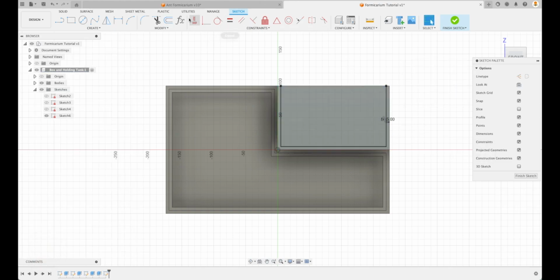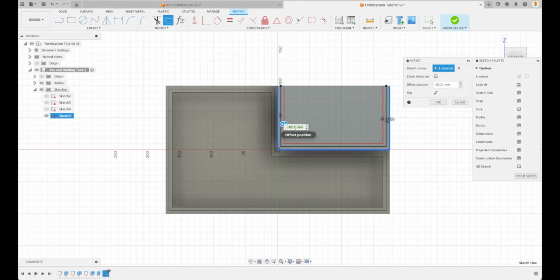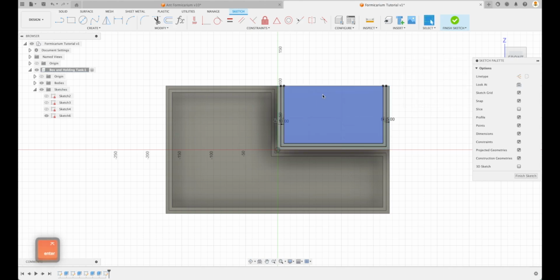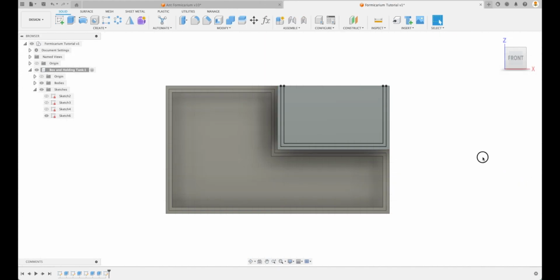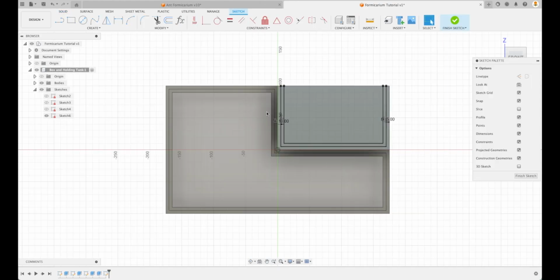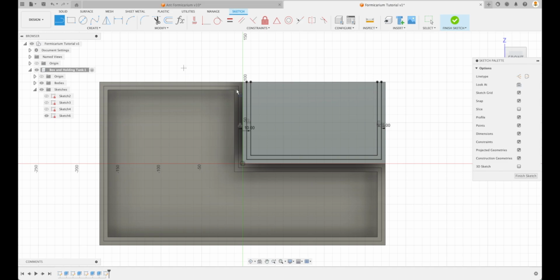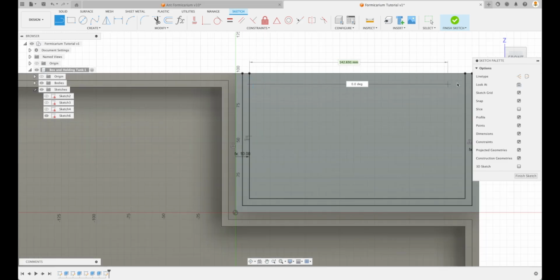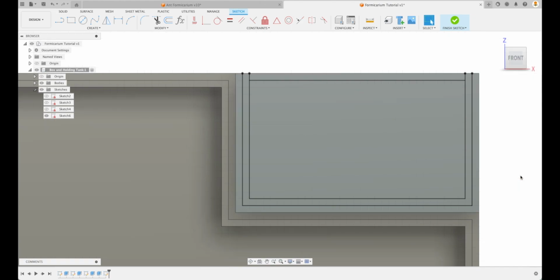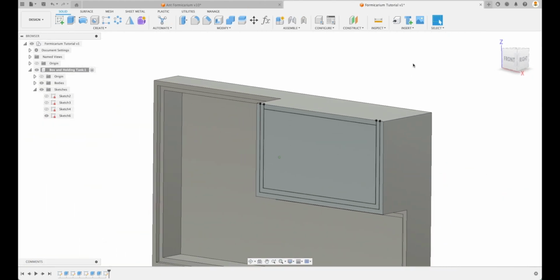And we're going to do the same thing to create another one. 1, 2, and 3. And this is going to be minus wall thickness times 2, I should say. There we go. And actually what we can do is go back to that sketch, and this second offset, this is where we can actually put this as a dimensioned value for our wall thickness right there. So you'll see it in a moment why we can select it like that. But this is looking great.